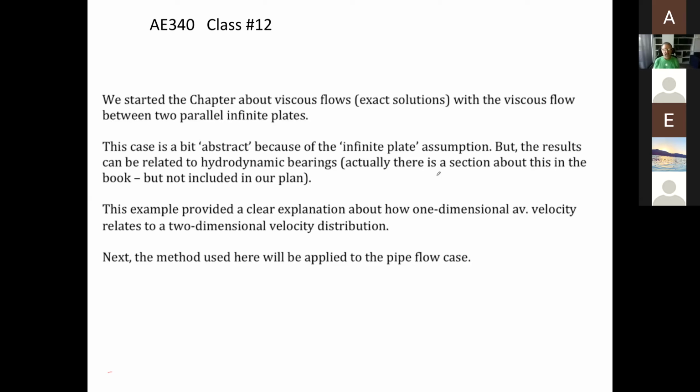Now, the hydrodynamic bearing is a little bit more complicated, because they actually have a change in the spacing, and therefore there's a change in the pressure. And that is incorporated in the section which is in the book. Again, this is advanced. A direct thing that relates to that is they used to have rotating discs in the computers, and they had the pickup arm. It was actually floating on the disk based on that principle.